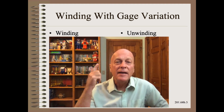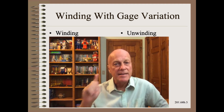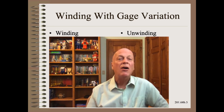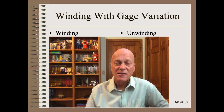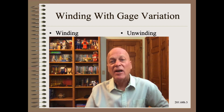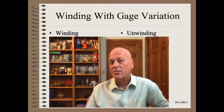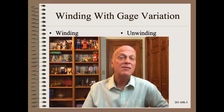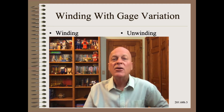If winding as loose as possible is not enough, then you must go and solve the root cause thickness variation coming from upstream. You must identify the specific element that is responsible and redesign or maintain that specific element to be less variable.